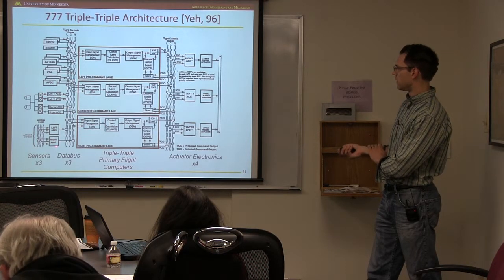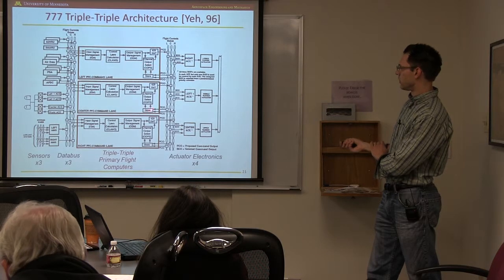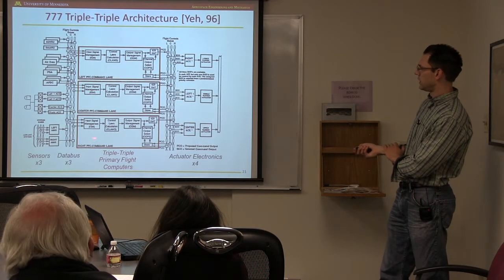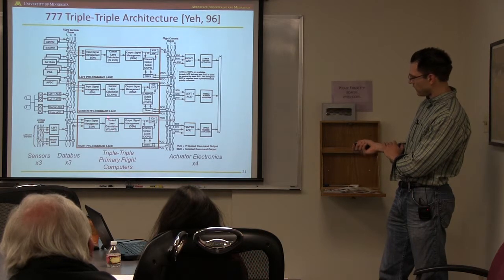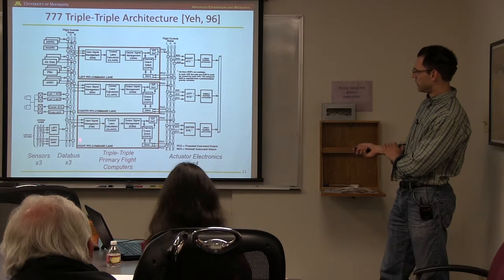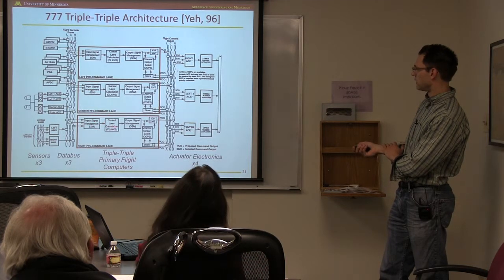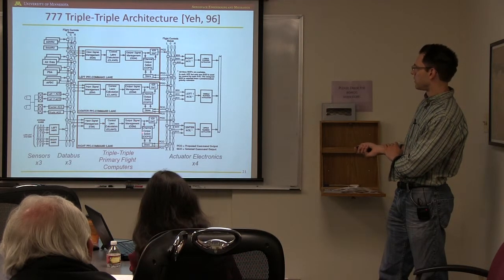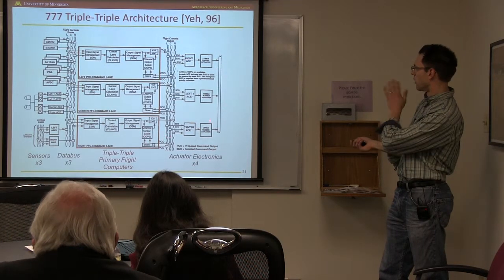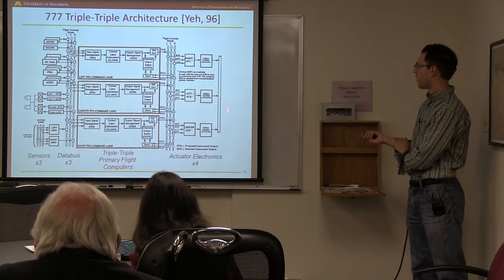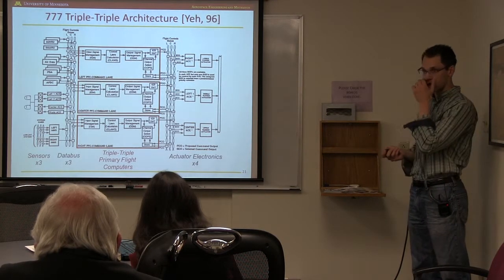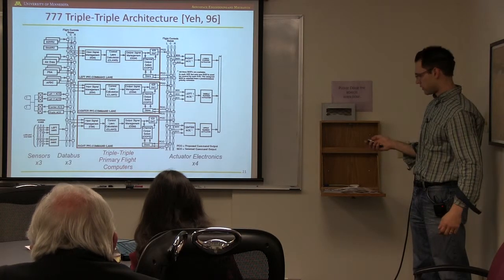Triple redundant data buses. All this information goes over to 3 computing boxes. So there are 3 separate computers that could fly the plane. And then here's your little controls piece that we like to design. It's sitting here in the middle, doing some signal management at the input and output sides. All 3 computers spit out some commands. It goes back on a data bus. And then this is supposed to represent the rudder, which is on the tail. The rudder has 3 separate actuators. So if one of the actuators fails, the other 2 can overpower it. Okay? So there are 3 separate computers.